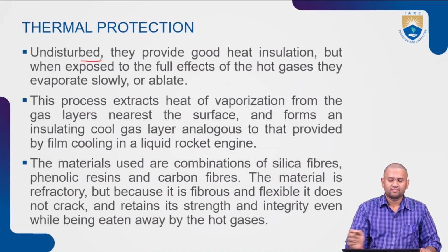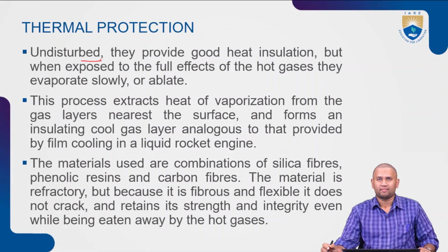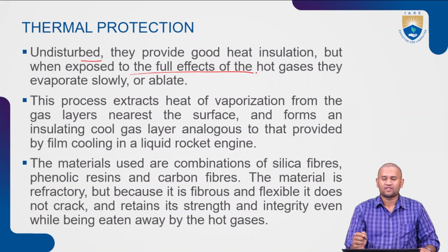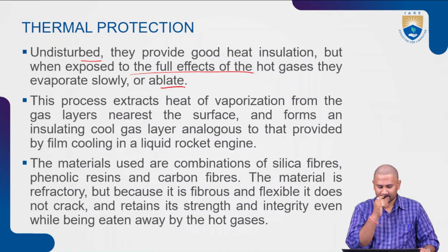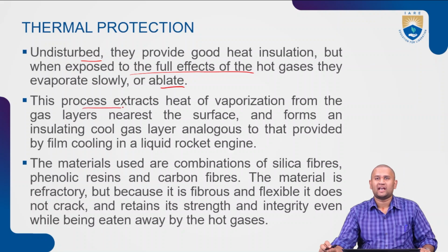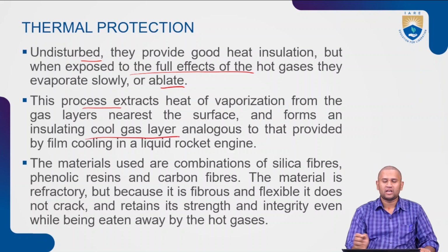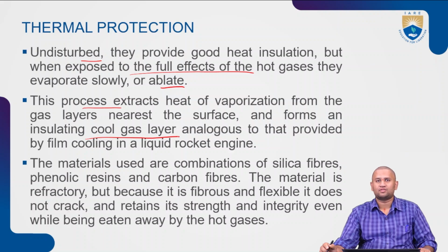Now, undisturbed, they provide a good heat insulation, but when exposed to the full effects of the hot gases, they evaporate slowly, or ablate. Right? This process extracts heat of vaporization from the gas layers nearest to the surface and forms an insulating cooler gas layer that is analogous to that provided by film cooling in a liquid rocket engine.